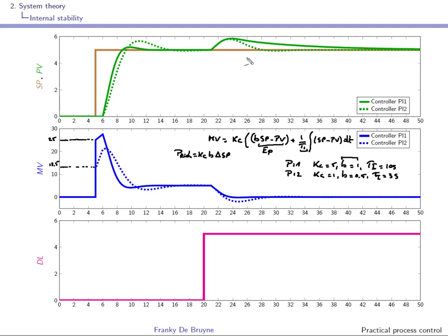But when it comes to the load disturbance, you can clearly see that the first PI controller, because it cancels the slow pole, has problems rejecting the load disturbance. As you can see here, the load disturbance has to disappear naturally with the time constant t. Okay, so it disappears roughly after 3 to 5 times t, so around 30 to 50 seconds, right?